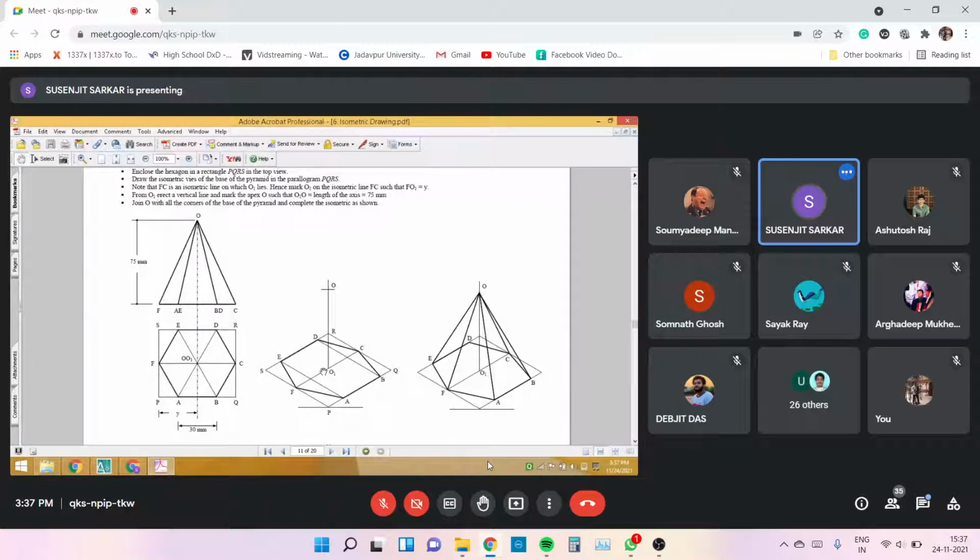So basically you are drawing the whole 3D. You are trying to draw a cuboid with all its maximum dimensions, and then within the cuboid you are trying to place the corners or the edges of the solids for isometric drawing. Suppose you have drawn a cuboid with this much base area and this vertical height.